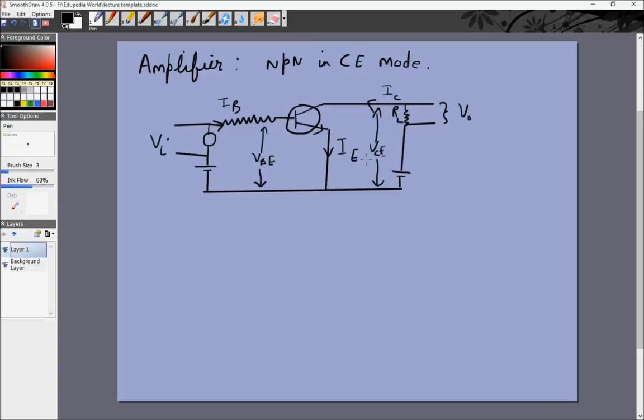emitter and the collector. So now what happens in an amplifier is that the electrons diffuse from the emitter to the collector. That's why the current is from the collector to the emitter, and this ends up creating a negative charge at B, because some electrons will be stopped at B and or will go from B to this side, right, from the base. So this creates a small negative charge at B which tends to block further electrons.